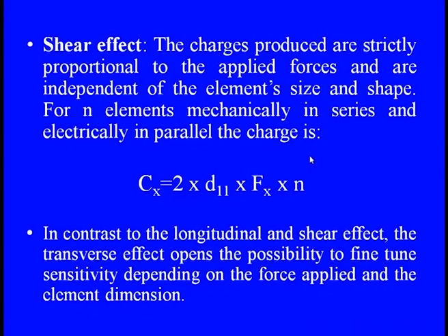So in contrast to the longitudinal and the shear effect, the transverse effect opens the possibility to fine tune sensitivity depending on the force applied and the element dimension, because this is a well structured pattern along the neutral axis. Here we need to take the shape and size into account. But in the other two, longitudinal and shear effect, the effect on these elements is independent of size. It only requires how many elements are arranged in series mechanically or in parallel electrically to determine the amount of charge produced.